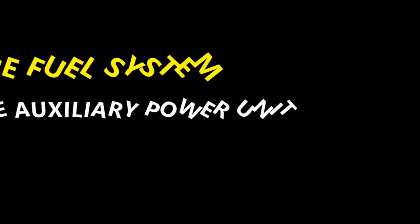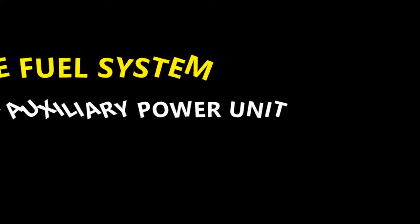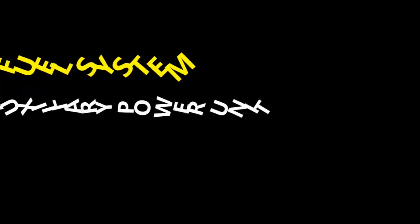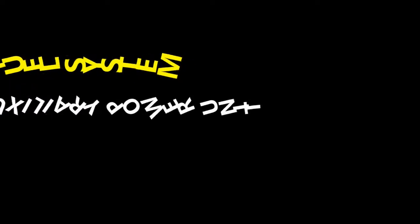I'm going to just go ahead and move on to the air intake. But before I do that, I do want to mention the APU master switch. When it's on, what happens? Remember I said we've got a signal going to the electronic control box that starts that fuel system to be fully automatic. Now at 7% speed of the APU, you're going to have that fuel shut-off solenoid I mentioned a bit ago start opening. Then from there, you've got fuel coming from the FCU pressurizing valve that will flow to the flow divider assembly.